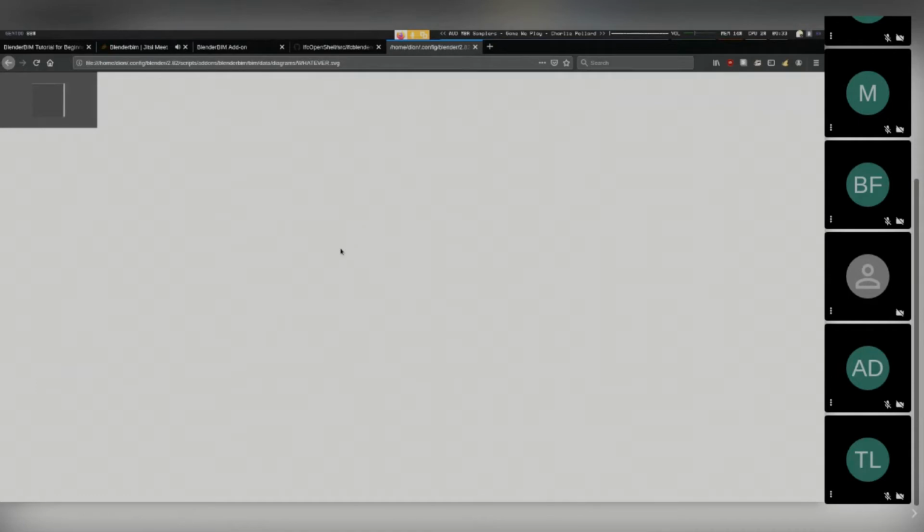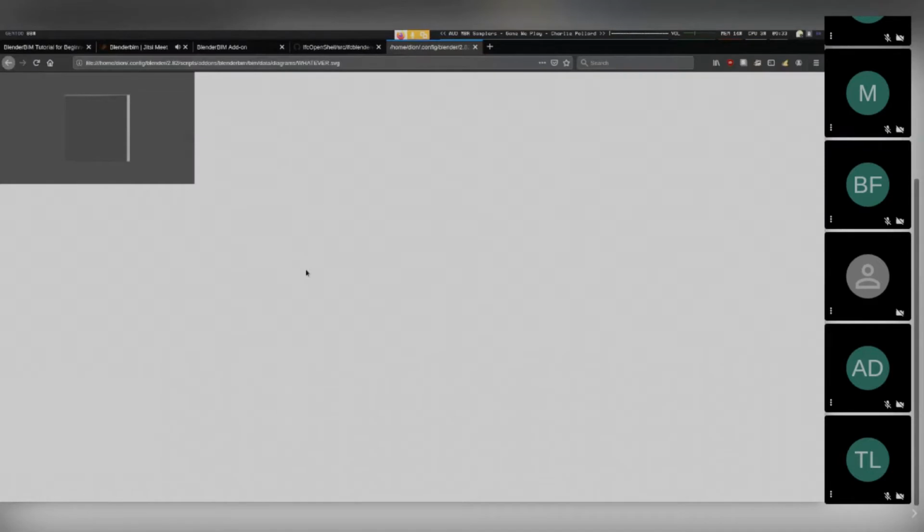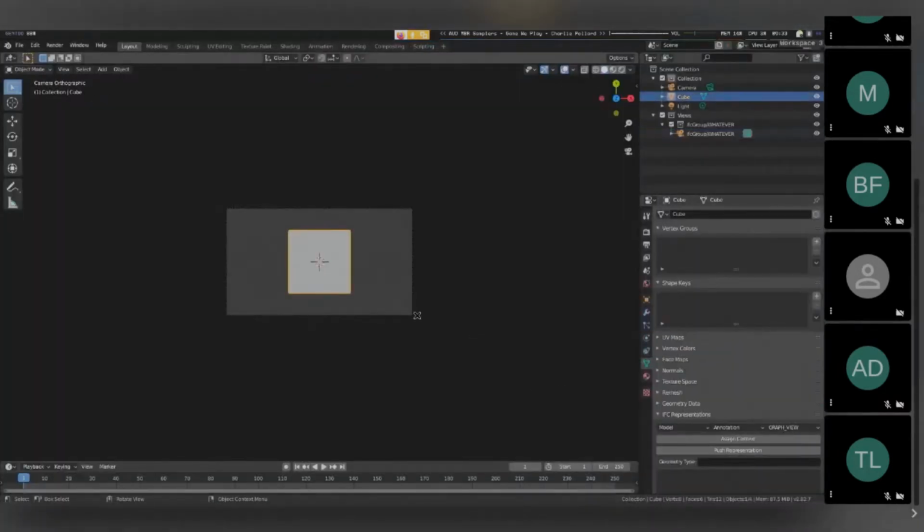By default, all it does is a Blender render, and it does a bit of calculation to make sure that it's 1 to 100. So if I print out that SVG on a piece of paper, and that's a 2 meter cube, that's 20 mil, I think, 2 centimeters on a piece of paper. If I change that to 1 to 50 and press the cut section button again, and refresh this, it doubles in size. That's because now it's 1 to 50. I'd have to check.